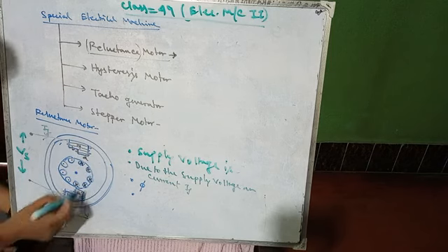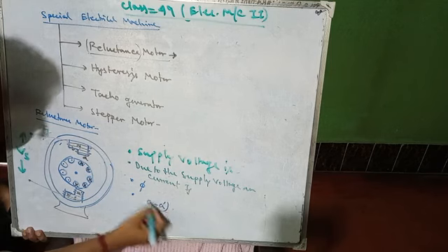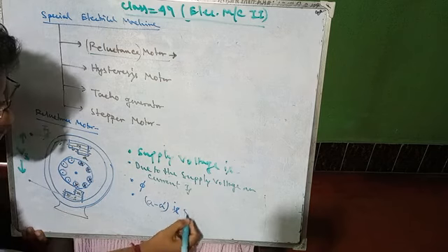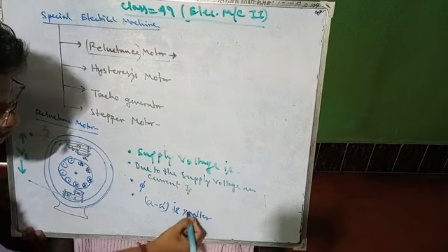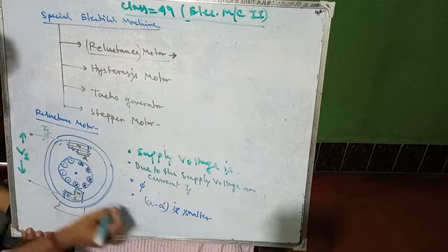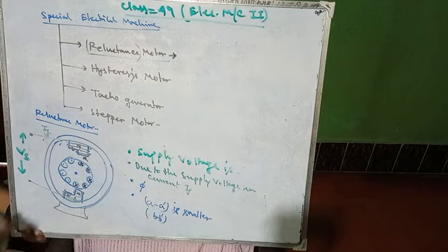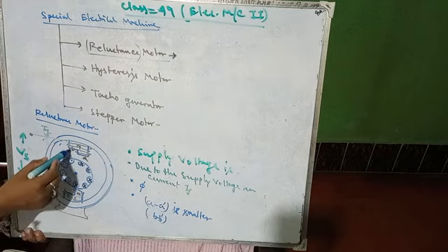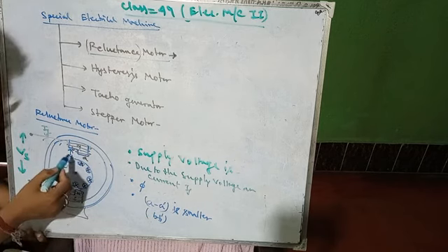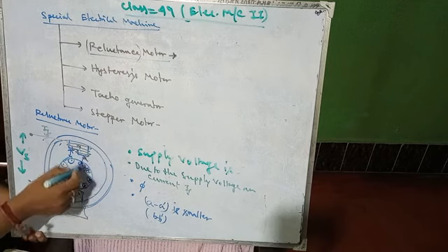The reluctance offered by the AA dash region is smaller compared to that of the BB dash region, because the air gap is more in the BB dash section and the air gap is smaller in the AA dash region.